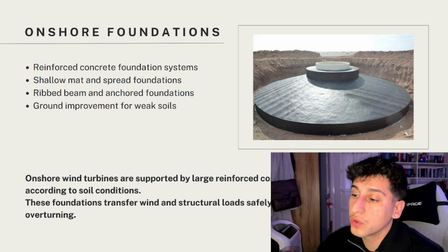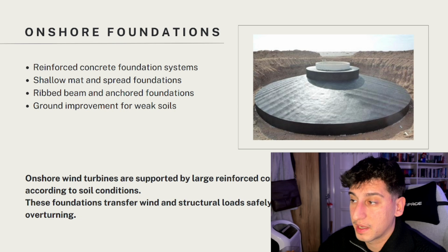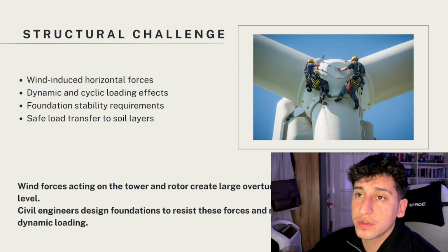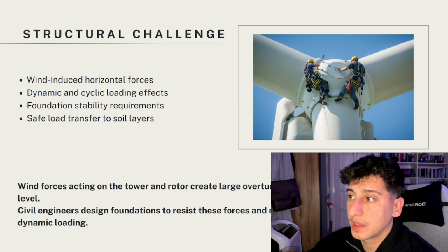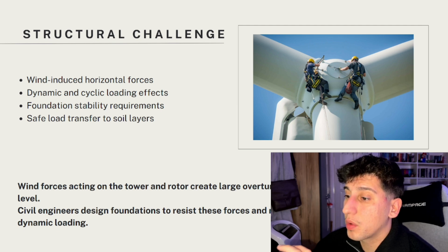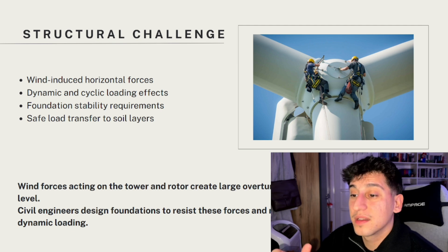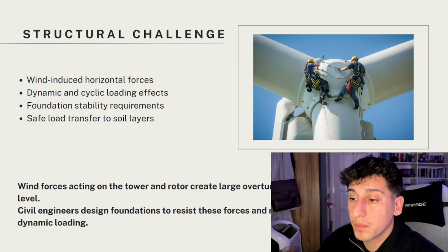In weak soil conditions, soil improvement methods such as deep ground reinforcement may also be applied. Of course there are structural challenges, and the primary one is the moment resisting overturning. Wind forces act on the rotor and tower, and these forces create large bending moments at the base of the structure.